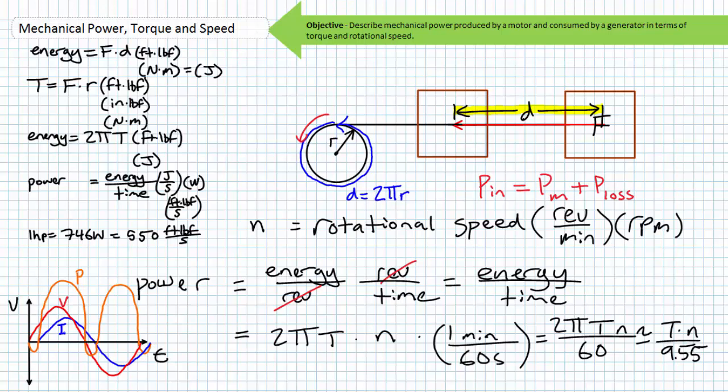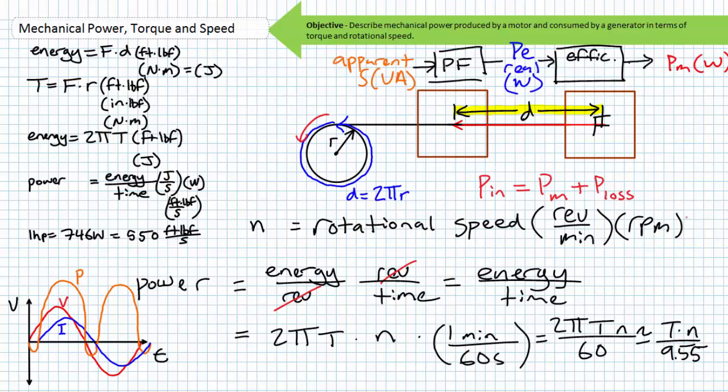Notice the terms I'm emphasizing: apparent, real, reactive. Some of you may be scrambling for your notes on these topics right now, but for now, just be comforted with this simplification. The real power delivered to the motor by the electrical utility should be some fraction of that power apparently supplied to it. This first hoop is known as power factor. Having cleared this hoop, the usable mechanical power produced by the motor should be some fraction of that real electrical power supplied to it. This ratio of useful mechanical output over real electrical power input is known as efficiency.